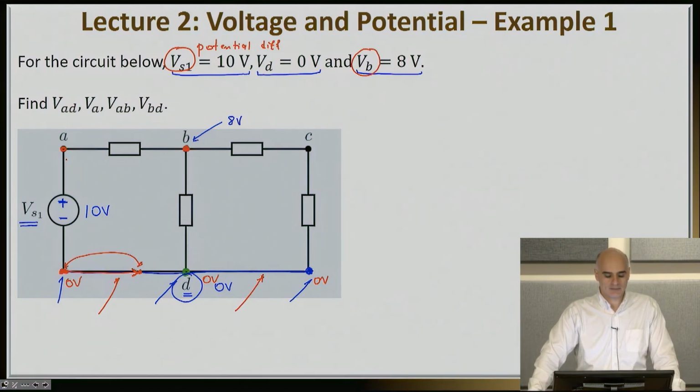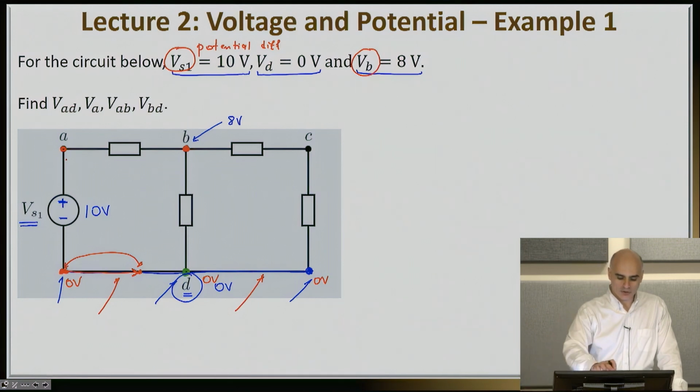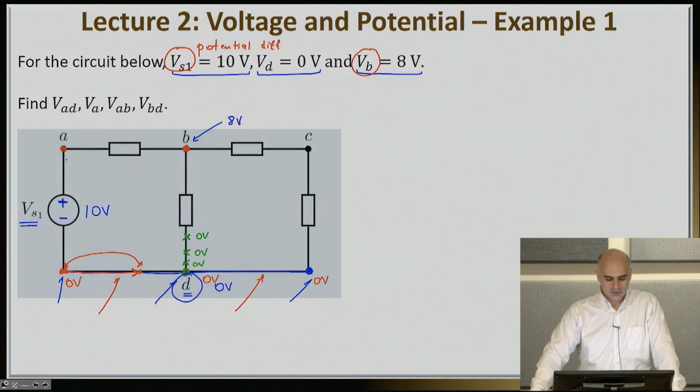Electrically, they are equivalent. The same thing, of course, you can say by looking at this node here and this node here: the voltage is the same. It's 0 volts here, 0 volts here, 0 volts here, and so on and so forth. So do not get confused that somehow things are changing. It doesn't matter how physically I draw the circuit. What really matters is the electrical potential of the nodes. All right, with these nodes, now let's go to our example.